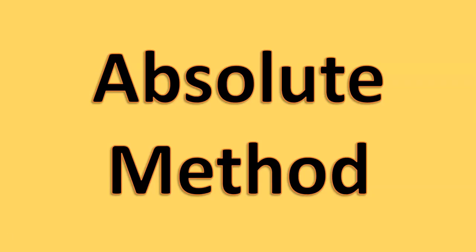Okay, the next method is going to be the absolute one. And this one is kind of particular in that you have to know exactly what points you're going to. So you can imagine that you're doing graphing that you may have learned, and you've got a 0,0 or an origin, and you're going to have to pick points depending on how far you are or close to that origin. So we're going to use the circle command, and I can also illustrate this one with the line command.